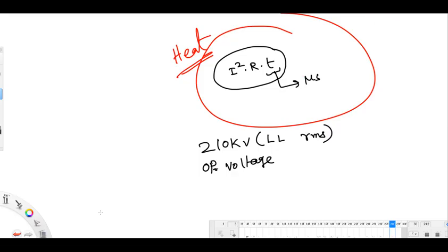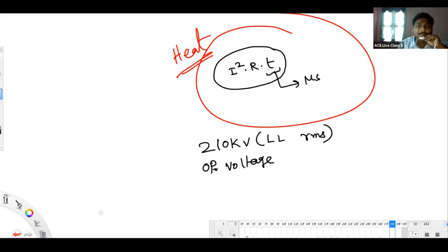The main reason for not selecting aluminum in the house is the voltage drop. Voltage drop is the main reason. One more thing, Imtiaz: from an investment view also, if you are using aluminum wires, the life of aluminum wire will be a bit less compared to copper.